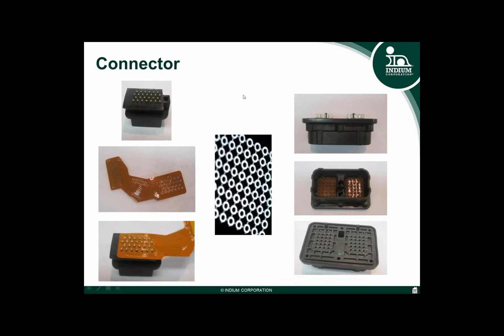Again, you can see a couple of automotive examples now using a flex circuit in this case, that's then joined and placed into an overmold with a connector on there as well. So this, using the flex connector, could be used with many different alloys. It could be used from the SAC alloys right the way down to the lower temperatures, depending on the characteristic of the flex circuit, but could be using tin bismuth as well.